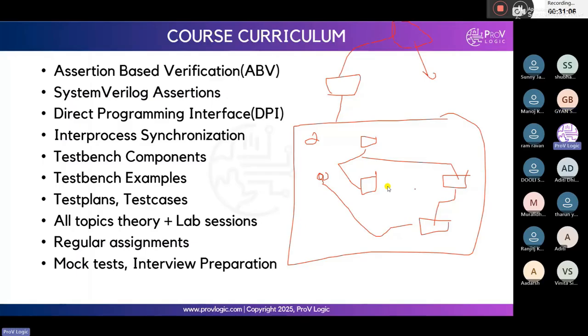In which case do we use C language for verification and SystemVerilog UVM for verification at SoC level? Can anyone tell? For pre-silicon, we will use mostly SV UVM, and for post-silicon, we'll go with C-based verification.